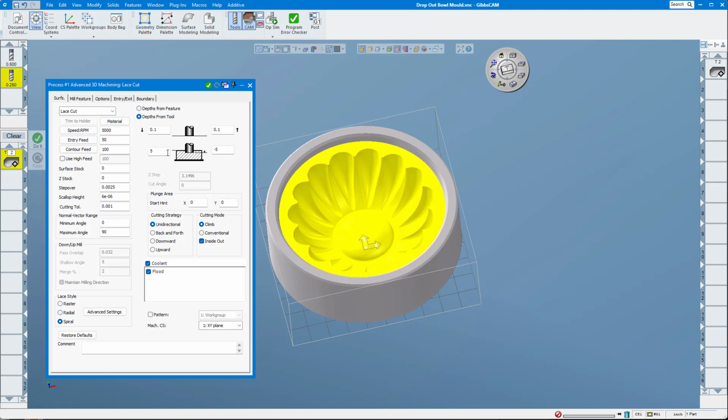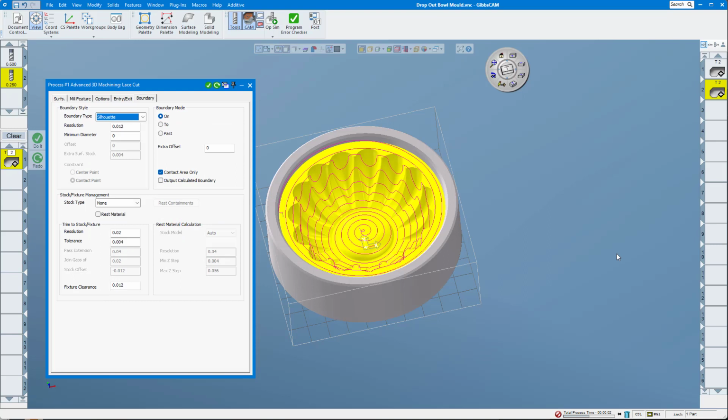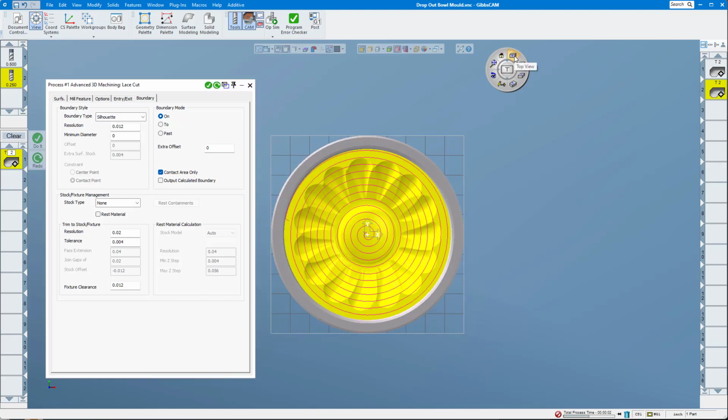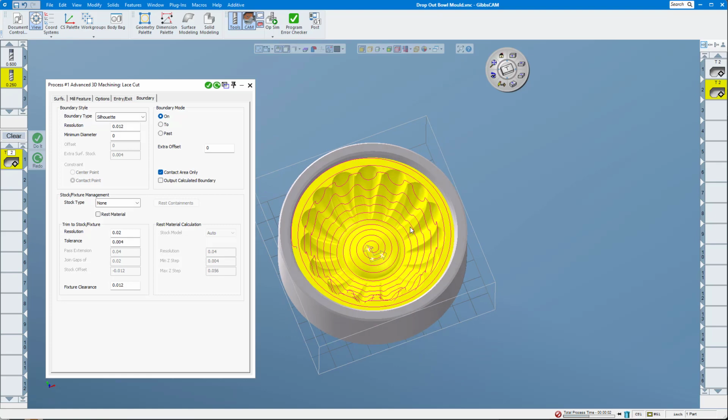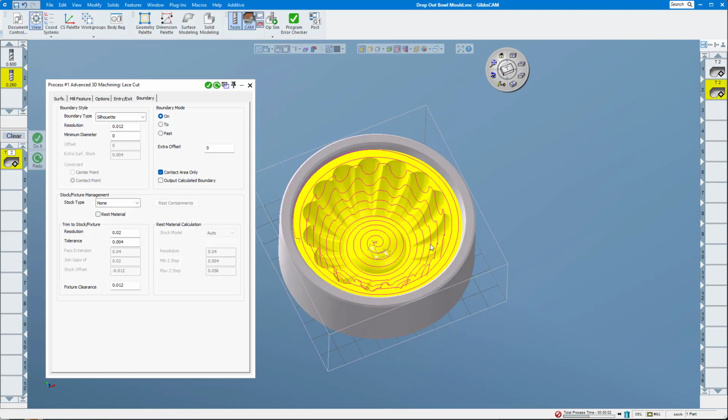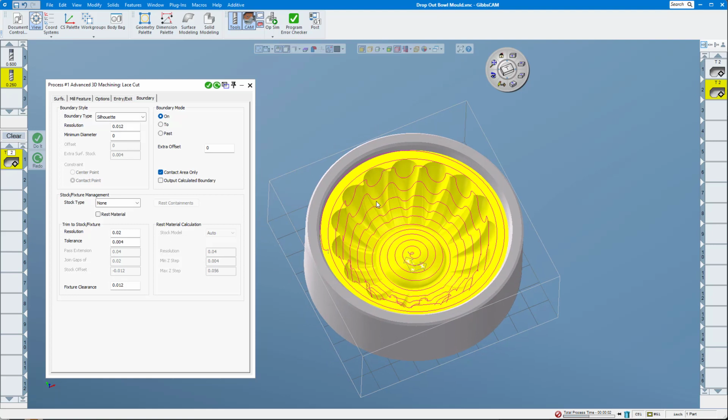Right, so let's go ahead and set this. There we go, as ordered from the menu, a spiral. This is really great. You're still going to get some really big scallops, even if you tighten this up a little bit, because of these steep walls. Steep walls in 3D machining really can cause a problem. They leave these really weird scallops. There's a couple different ways to approach it, and really the name of the game is you want to do the least amount of post work as possible, right? You want the machine to do all the work for you. That's why we're going over all this.